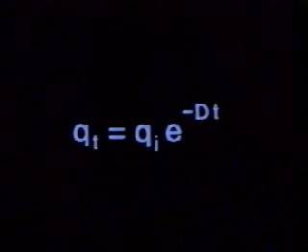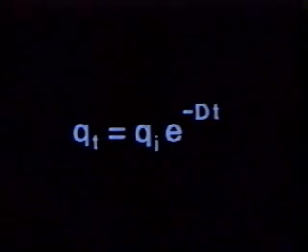We are often asked to quote a well's decline rate on an annual rather than a daily or monthly basis. This can be done if we make several observations about our rate-time equation. We will begin by assuming that our time, T, is in years, and our constant, D, is in units of 1 over years. Units for production rate for this equation alone may be given in barrels per day or barrels per month, provided the units for time in the exponent are the same. The consistency of units must be maintained in the exponent.